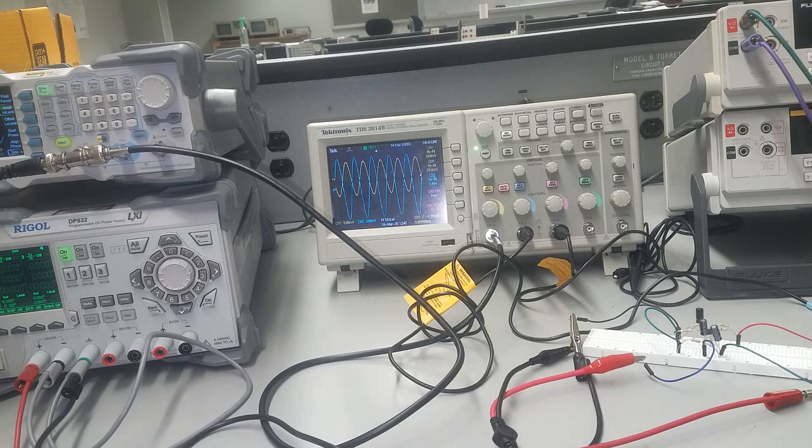So that's what I'm going to do now: play with the source resistance until I get the proper gain, and once we get the source resistance, then we go back and measure the DC values. So it's kind of an iterative process. Design is always an iterative process, and I want you to see that. So now we are going to change the source resistor value to 20K, and let's see what we get when we do that.